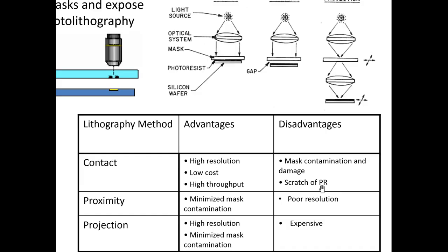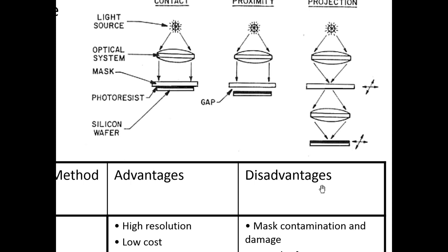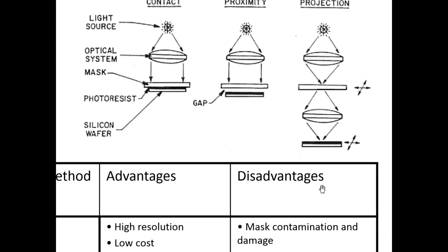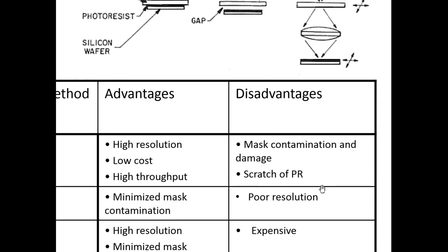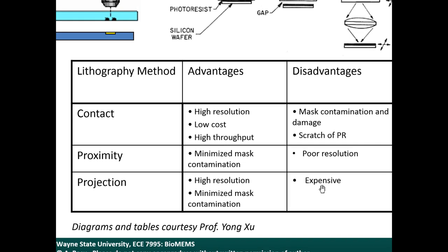Because let's imagine that there's an opening. If there's an opening in the mask, if there's a hole in the mask, the light will actually spread out from there. It doesn't go straight through it. Because of diffraction, it actually spreads out like a cone. Okay, we'll talk more about that later. That's actually what limits the smallest feature size in optical lithography.